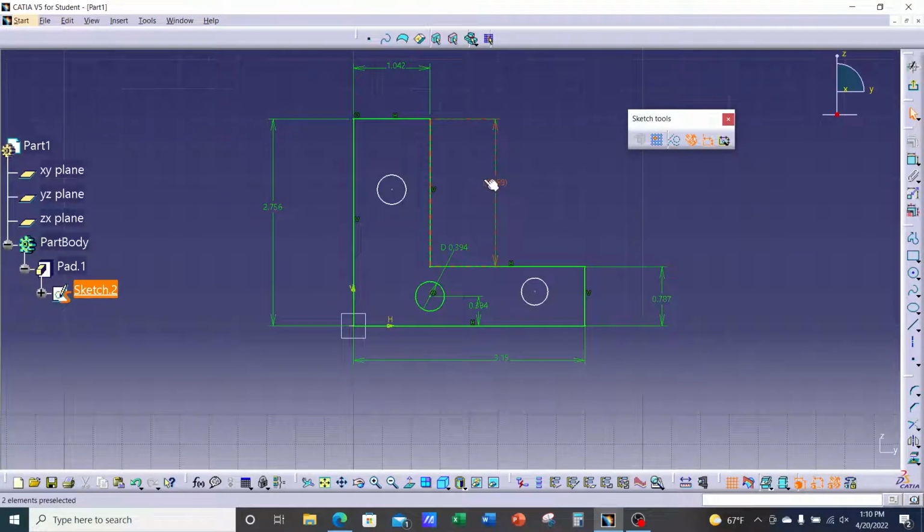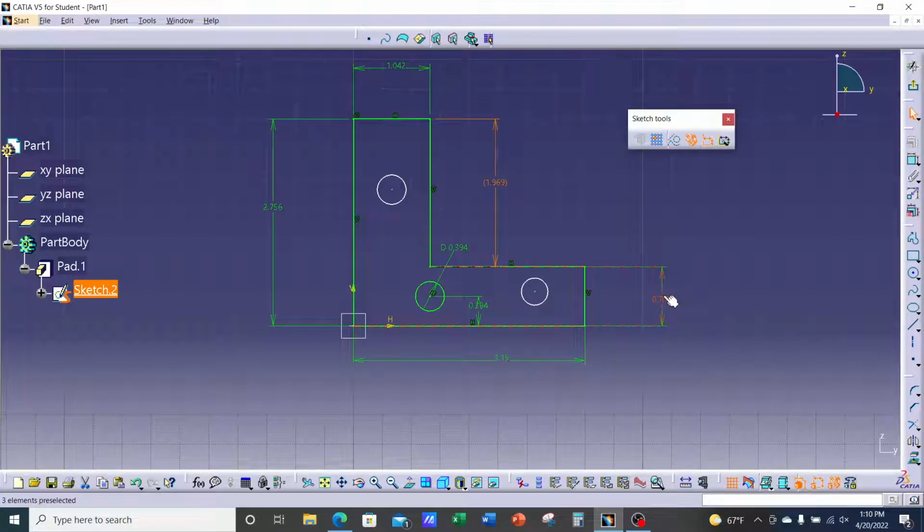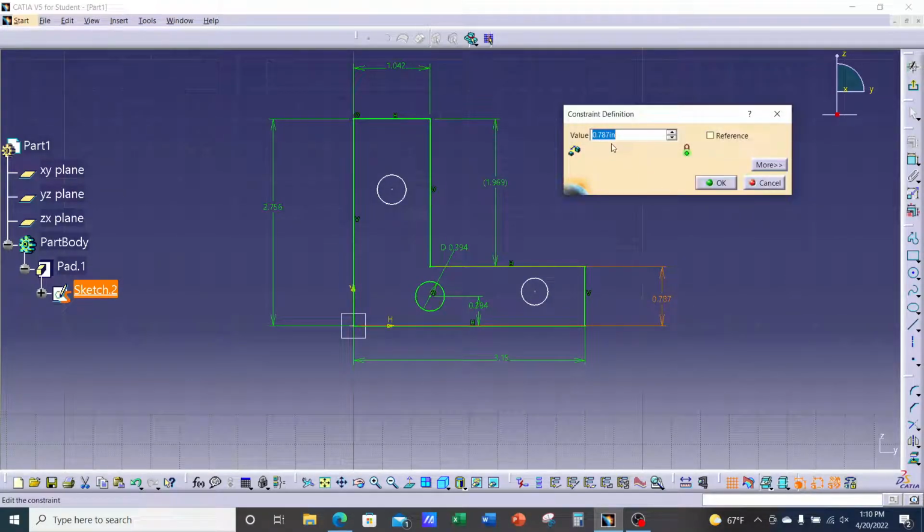So now all these are in inches. If I double click on it, you'll see it has the IN for inches. Let me cancel that. Double click. It has IN for inches, right? By the way, you can always override the units. So if I wanted to type in millimeters, I can say, hey, I want this to be 12 millimeters.